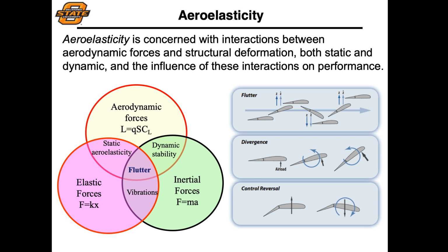In this case, we're looking at the overall science of aeroelasticity, which is looking at a combination of both the aerodynamic forces and the structural deformation, both static and dynamic, and looking at the interactions that are going to occur between these. So when we start to combine all these together, we're going to look at the aerodynamic forces, the elastic forces that we're going to see from structural deformation, and then the inertial forces given the weight of our structural design.